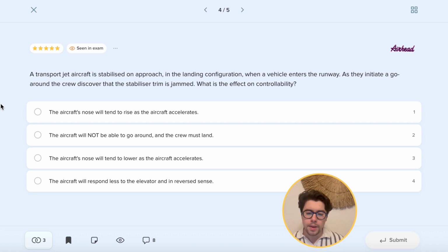However, with most aircraft we should also consider the fact that the engines will have a great moment, especially the underwing engines used in most jet aircraft will generate a high nose-up moment. However, not thinking about this right now and not making any assumptions, just remember that as you accelerate, you need to change the trim, and also as you decelerate. So here, as you are going around and as you accelerate, you increase the lift, and this increase in lift actually will make the nose go up.